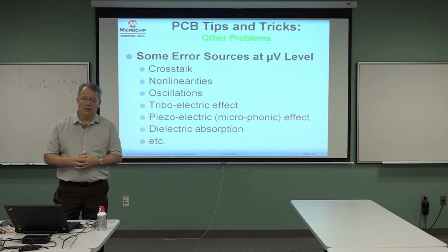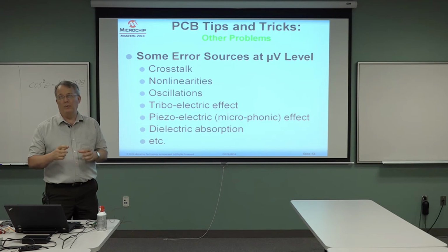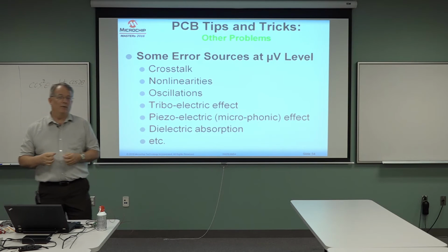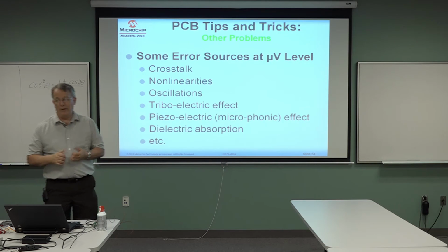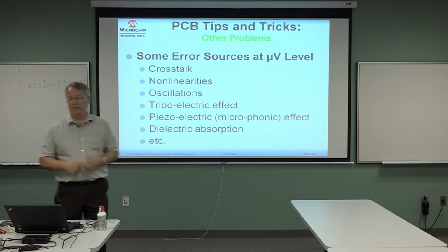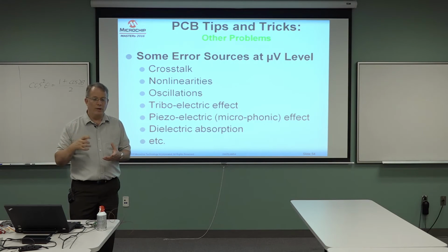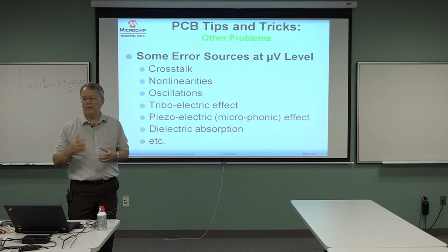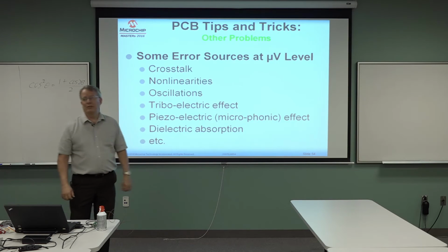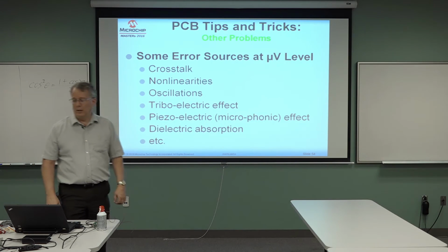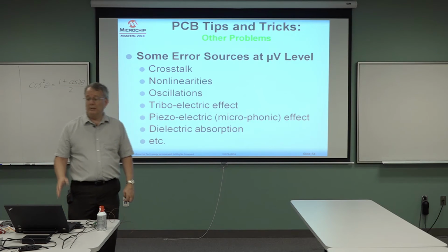So that's an example of a nonlinearity that will cause a DC shift. The more common nonlinearity that causes a problem are the ESD diodes at the input of all op amps or any type of amplifier. And by the way, those diodes are incredibly fast. They have to deal with ESD events that are on the order of a nanosecond in duration. They're very fast, they're very nonlinear, and they can conduct a lot of current. So what that does to an amplifier is if I have radio frequency interference, some kind of RF crosstalk, that'll be rectified by those diodes, and that rectification causes a DC offset to be added to the amplifier. I have seen as much as around 600 or 800 millivolts shift in the offset in particular applications. So that's something to be aware of.